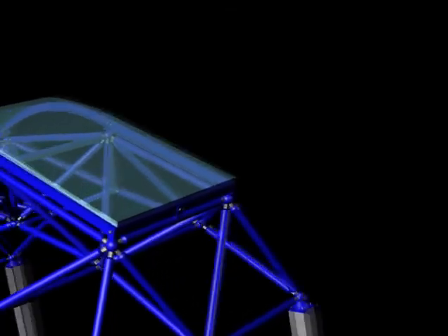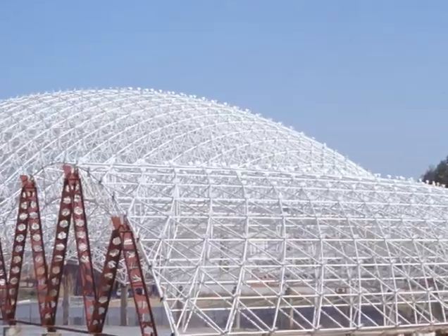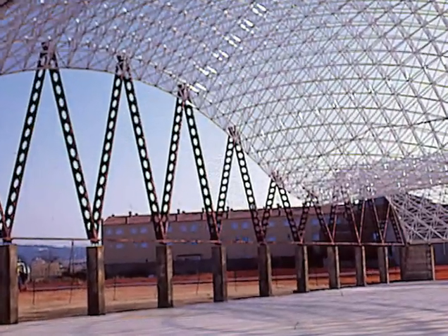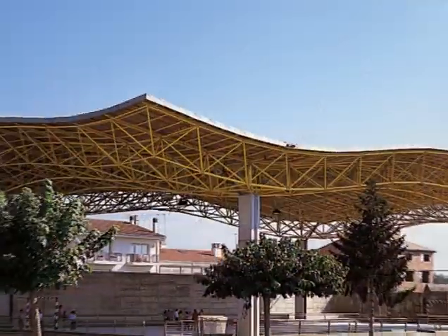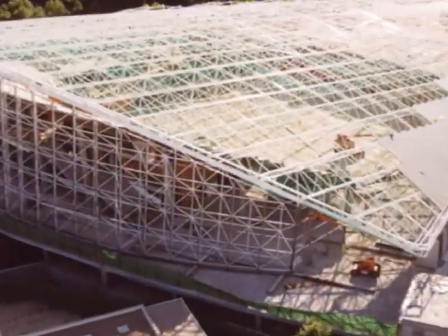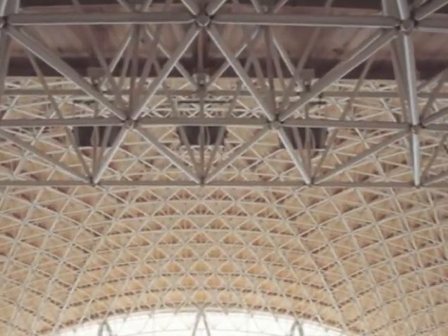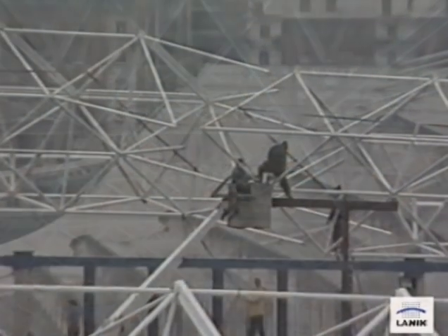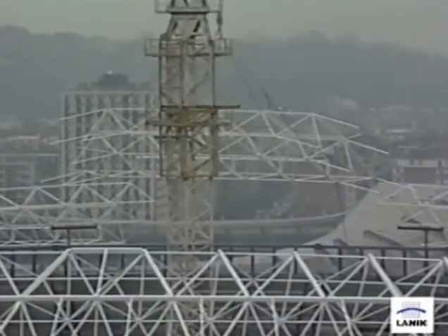The pyramid types are chosen depending on the structure of the building. For instance, when we have a structure like this, which is full of curves, it is easier to use the pyramids with a triangular base, simply because they fit better in the structure. Once the space frame is ready, we put together the purlins and knots, which are placed on top of the space frame in parallel.